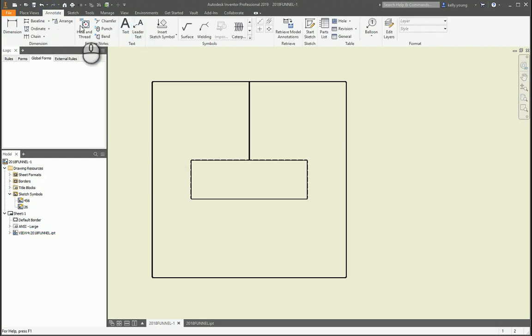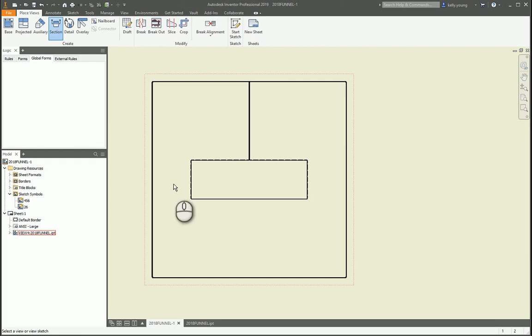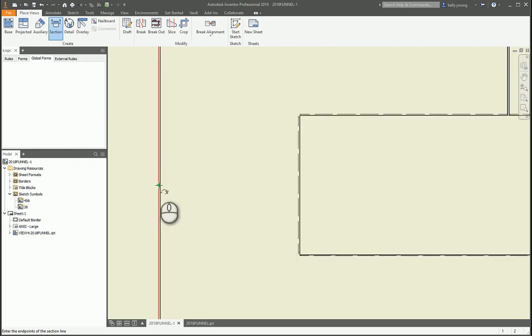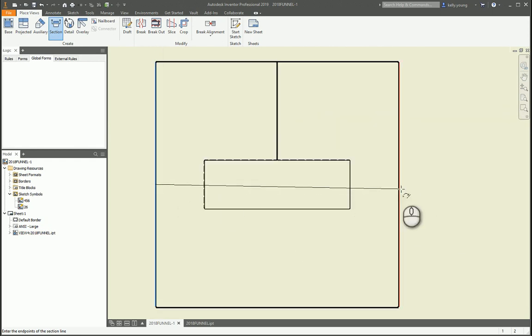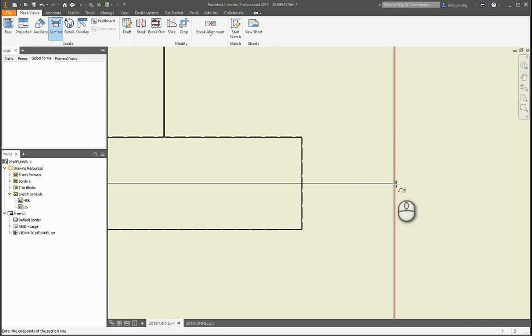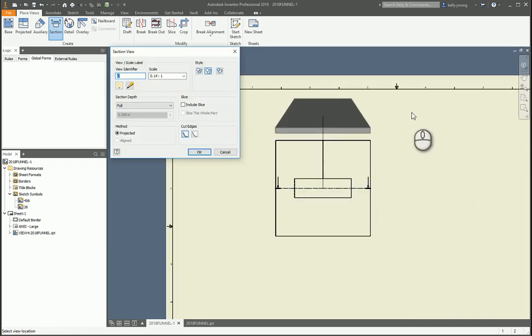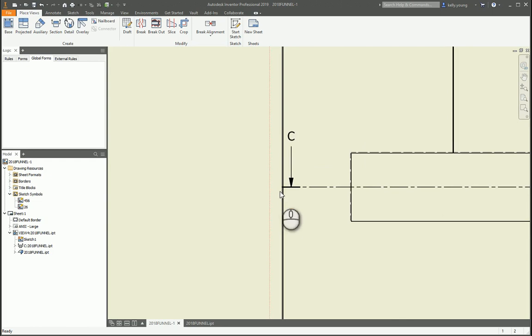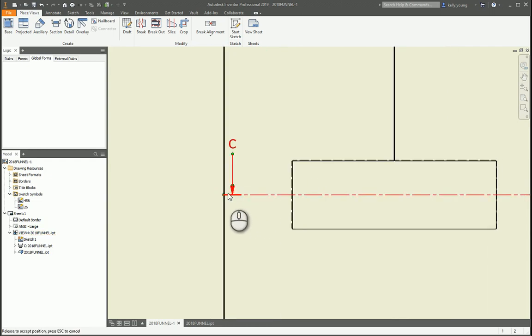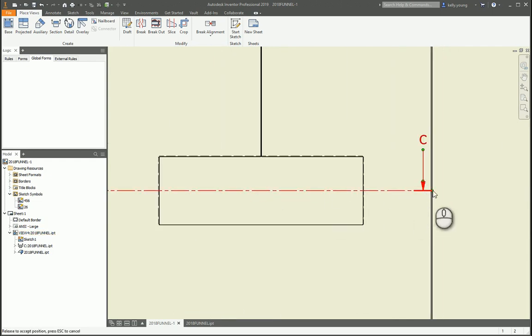So what it sounds like you want to do is create a section and then have the section line have like a custom leader or a line here. So I'm just going to go and create our section real quick. So you'll notice that basically this line is on the dots and it has the dash.